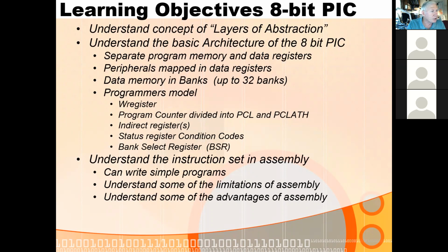For this particular chip, there is some program memory, which is implemented in Flash, which is a type of read-only memory. And then there is some random access memory that's not ROM, that's RAM. And then you have some special function registers, which allow you to make the chip work and use all the peripheral devices.